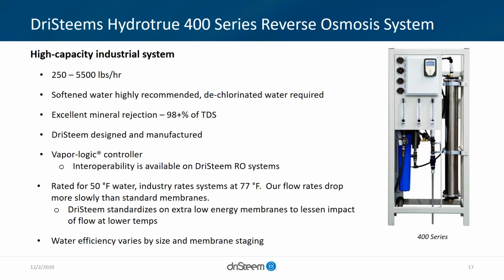Same with manufacturing and designing the 400 series RO. We definitely recommend softened water to extend the membrane life, which we do have pre-treatment both for the softening and dechlorination.